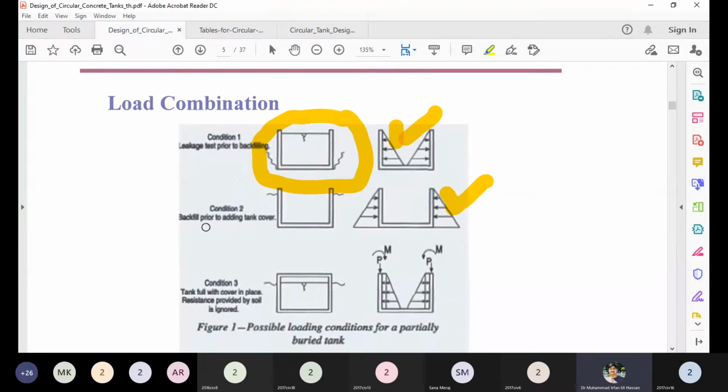And there is one more condition which is not all the time practically followed, but if the tank is covered and uncovered again and again, you have to see sometimes that the tank is covered also, because when you put down the fixed cover or hinge cover at the top, the additional load is also produced due to this cover, the additional movement and the axial load is also produced, which is not present otherwise.